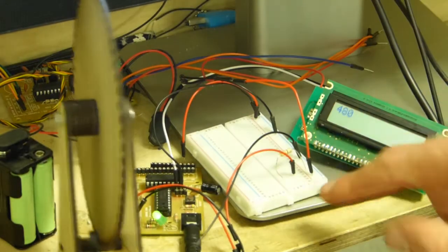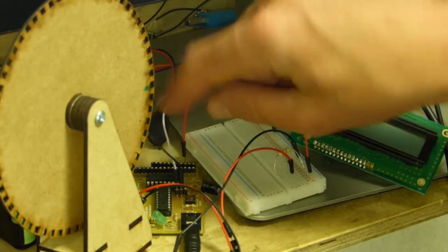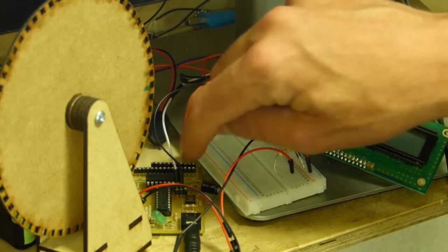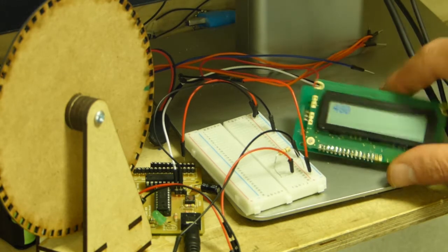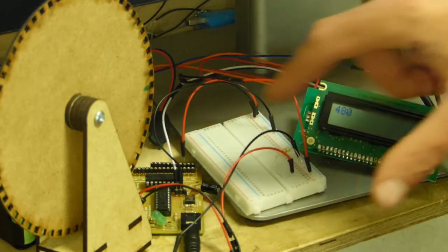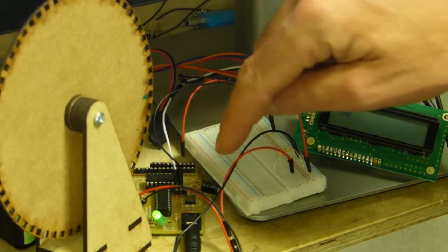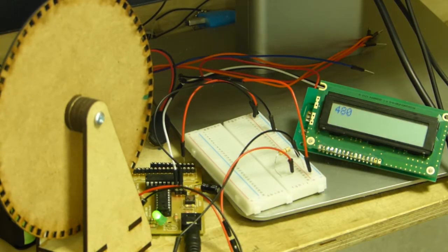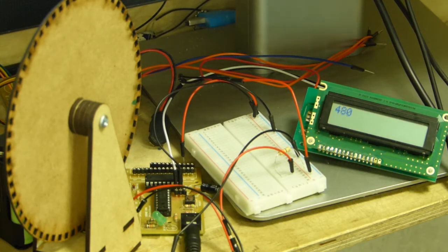The emitter is just going straight off this rail here, which, like the other times, is just plugged into the output voltage. So I've just got a plus volts here off one of these common rails going onto this plus volts rail, and that's also powering the LCD as well as the emitter and the detector. The detector is plugged into one there, but basically the detector is just sensing an analog value. It's going into this input AD0, and we're reading an analog input there. So rather than on or off, it might work as on or off, but just in case we don't get the full range of off or on, we can just detect an analog range here.